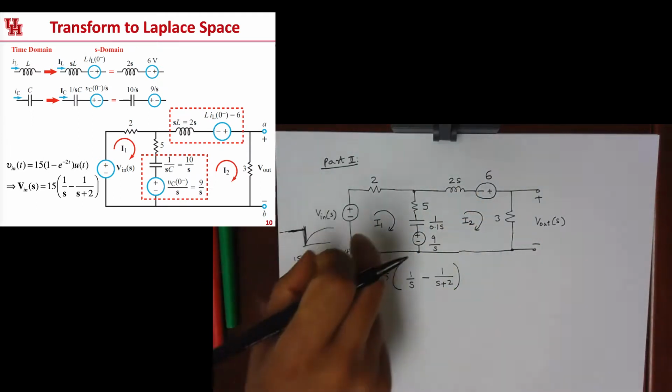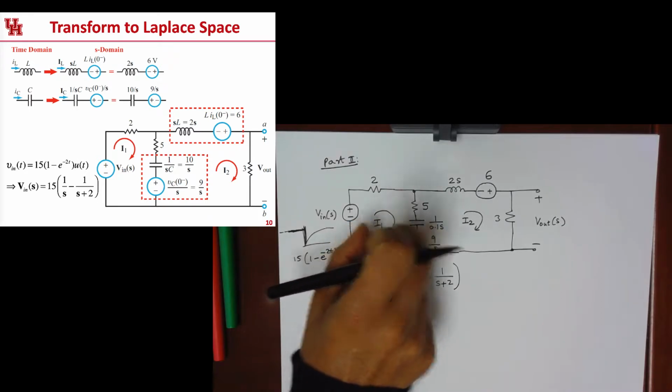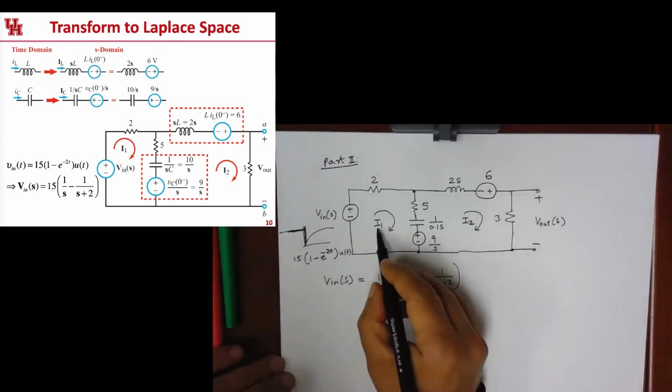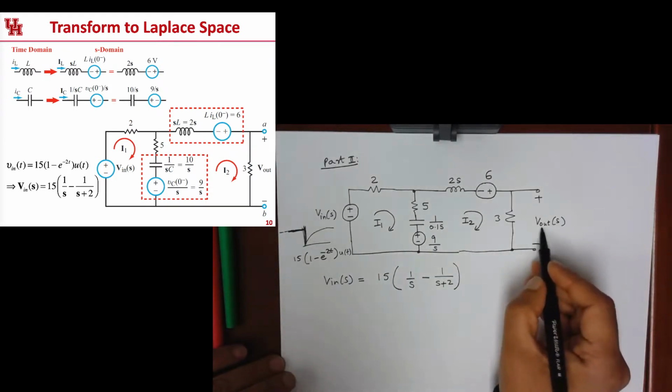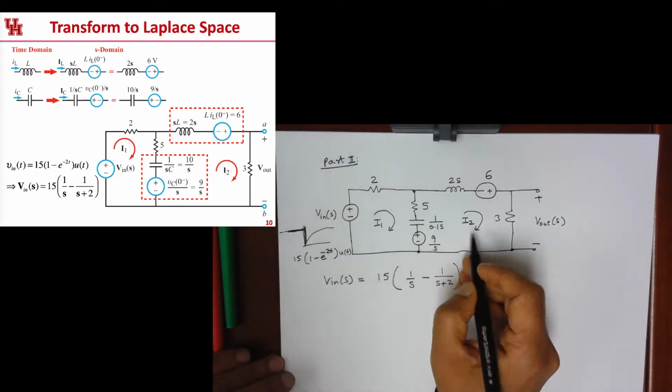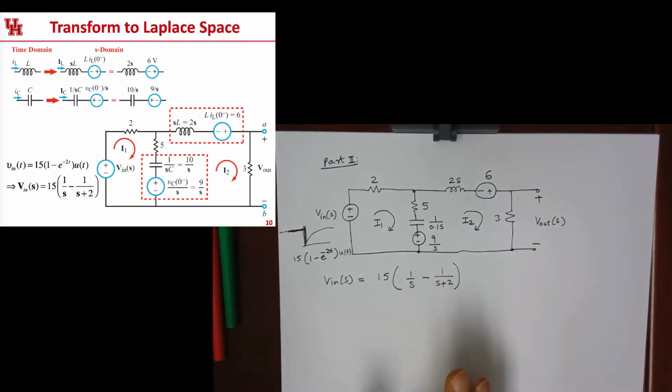And in order to do that, we're going to first solve for the current I1 and the current I2. Now, we don't really need to solve for I1 because all we need is the output voltage. So it's enough if we simply solve for I2. Let's keep that in mind. So basically, let's start out by writing down the Kirchhoff's laws for this circuit.